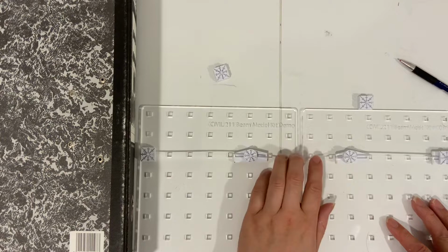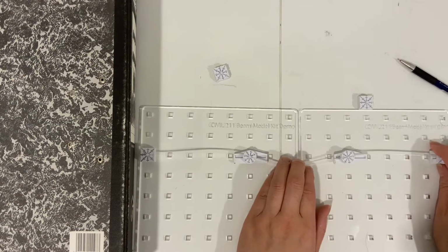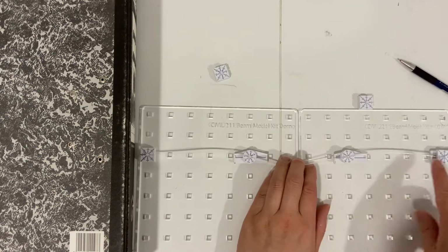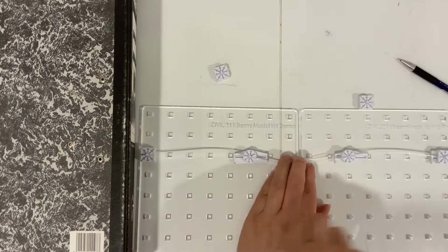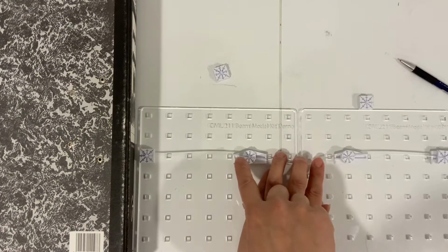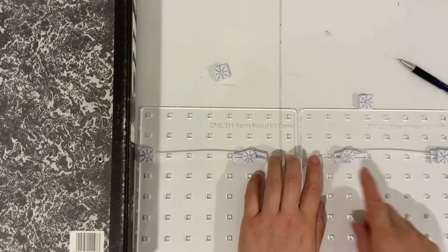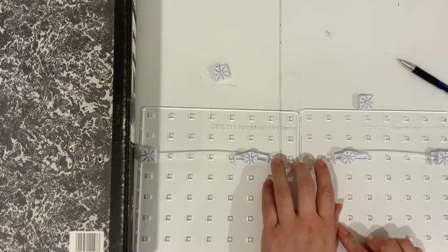So if I apply the load there and allow that one to move in, then you can probably see that would have been the right hand side column, which would have been down there. That would have been the left hand side column going down there, and we can see that it's almost the same. So that's a good enough approximation for how that portal frame can be analyzed.